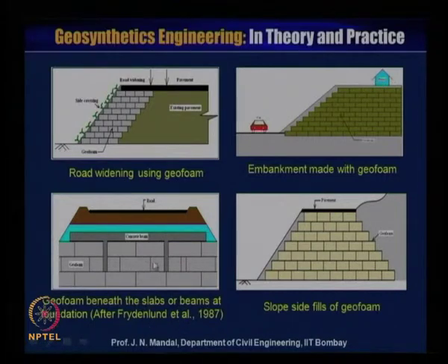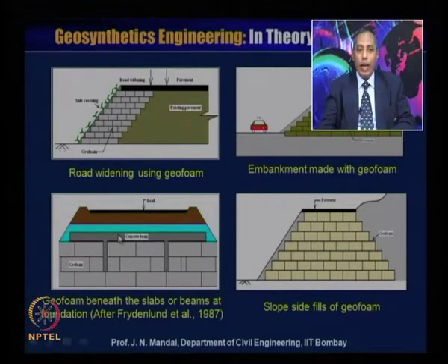Here is the geofoam beneath the slab or the beam at the foundation, after Farid and Wright, ETL 1987. So here is the concrete beam, and here is the geofoam material. This geofoam beneath the slab or the beam at the foundation will help you to reduce the pressure.